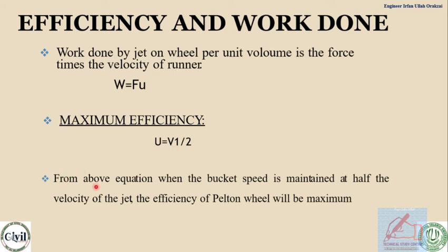From the above equation, when the bucket speed is maintained at half the velocity of the jet, the efficiency of the Pelton wheel will be maximum.